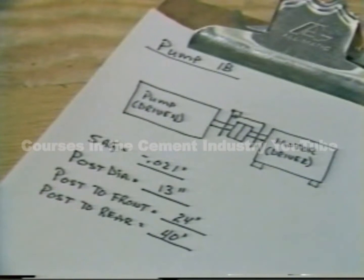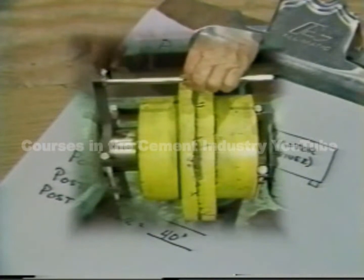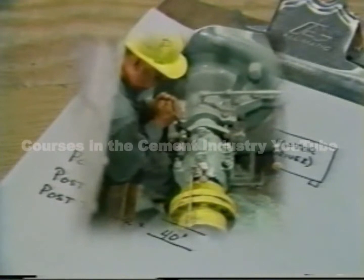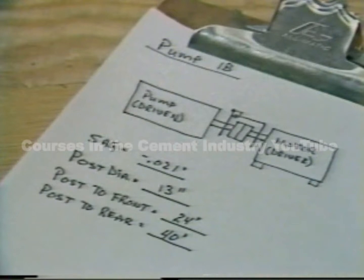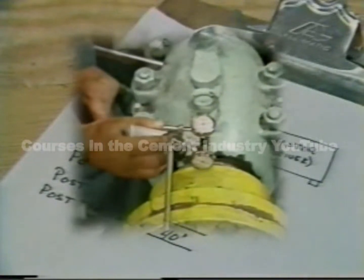Before we continue with the job, let's take a moment to recap what we've seen. The dial indicator brackets must be mounted securely to ensure a rigid fit. Any movement of the apparatus will throw off the readings later on. Once the dials are mounted, they are rotated to the top, so we have a starting point for all readings. The remaining reading points are marked 90 degrees apart so that the readings will be taken at the same spot each time.